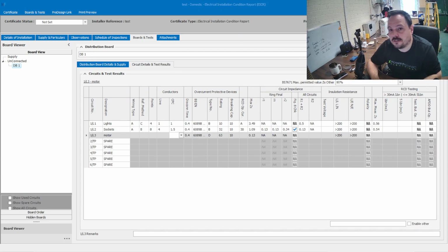You have a difference in tolerance within the test instrument as well when you're making your loop impedance measurements. I think it's about 10%. So that's a factor. We've also introduced the bonding connections as well with the live measurements. So we've got water and gas services that are both metallic into this unit, so they're going to have an impact. There's no other parallel paths because the trunking and containment doesn't go back to the consumer distribution board. It's separate, so it's not really providing any means of additional CPC into the circuit, so you're not going to see any of that. And yeah, that's just an interesting observation.